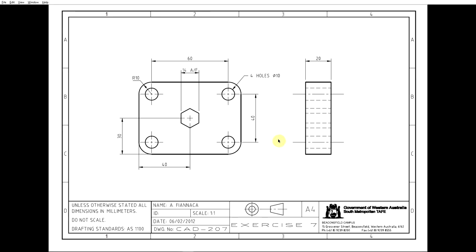So popping back to our drawing, let's go and have a look. What do we know about it? Okay, it is 20 wide, and it's obviously going to be 60 high from top to bottom, because this is the right side view. Now, how far away does that need to be? Okay, it doesn't really matter at this stage. What we are looking at is in terms of the final drawing later on. You don't need to worry about it for this drawing. But you'll notice we're looking for a balance, sort of see how we've got a balance of blank space either side and in the center here. That's pretty much what we're looking for.